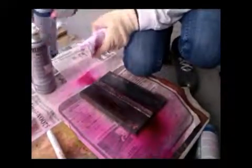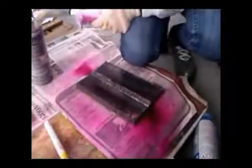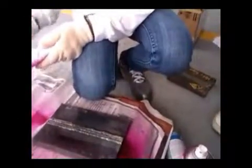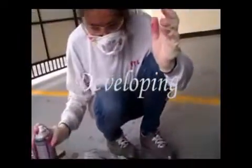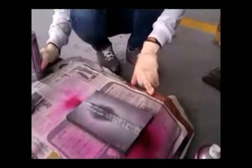If excess penetrant is not properly removed, once the developer is applied, it may leave a background in the developed area that can mask indications or defects. In addition, this may also produce false indications, severely hindering the ability to do a proper inspection. Also, the removal of excess penetrant is done in one direction, either vertically or horizontally as the case may be. Then apply an even coating of developer on the surface.